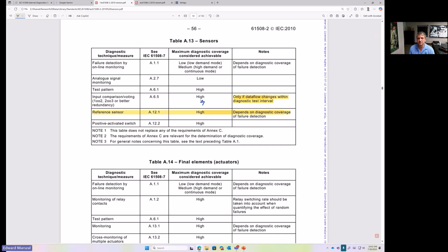What are the chances that that diagnostic is going to help you at all? It's not. It will only be able to tell you that that dangerous difference between the signals has occurred when that level starts to go up. And when the level starts to go up, you've got like a couple minutes before that liquid is in the compressor. You can't do anything about it.